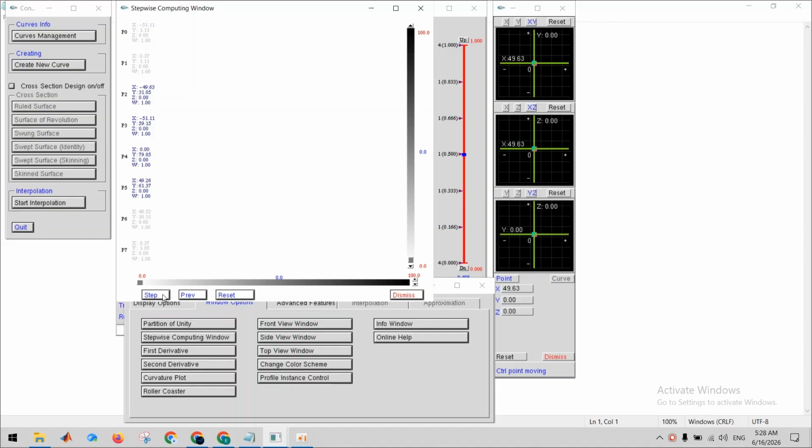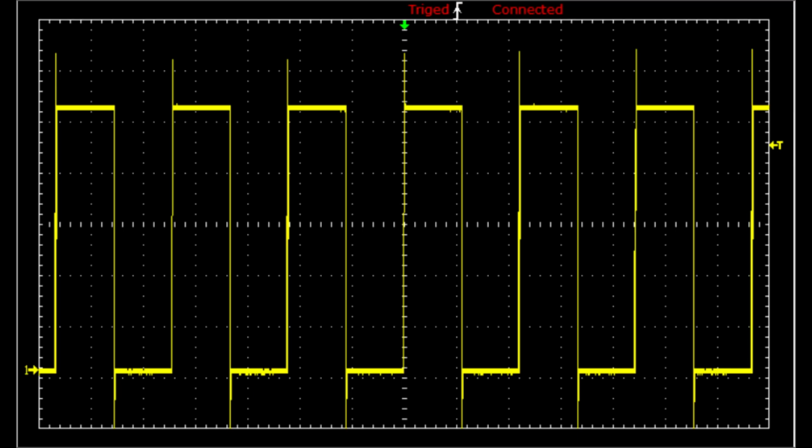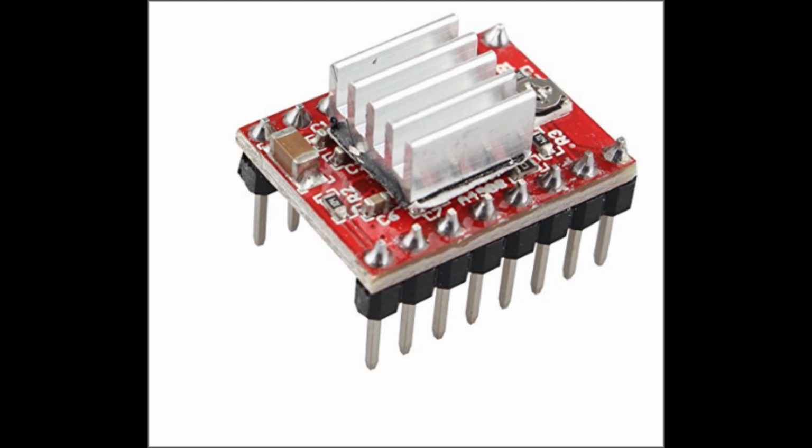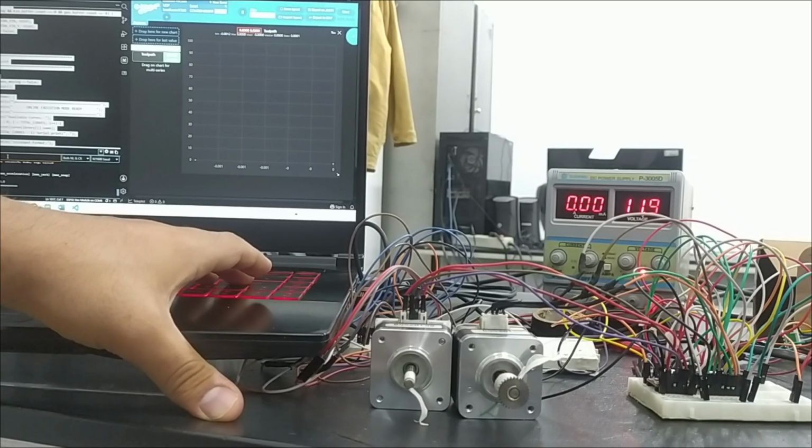As our flowchart shows, we plug that parameter u into the B-spline equation to get the exact x and y coordinates. Finally, these calculations generate the exact electrical pulses for the A4988 drivers, timed perfectly by the jerk-limited profile to guarantee a smooth acceleration.